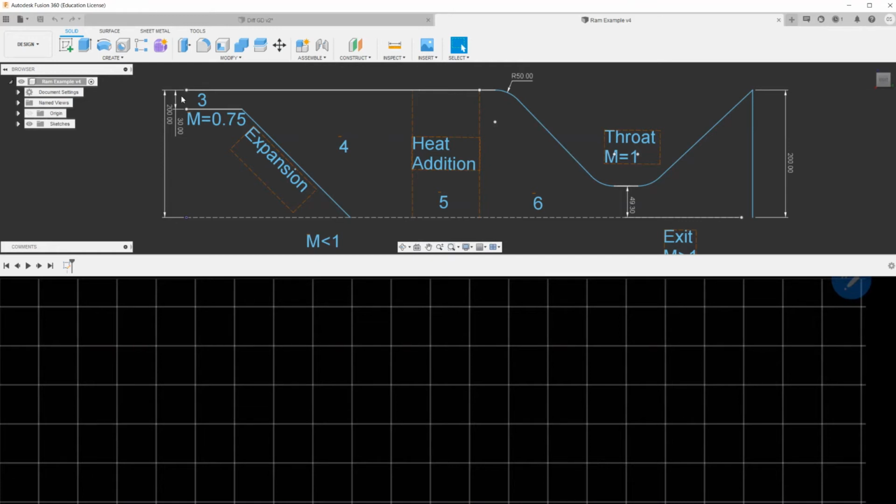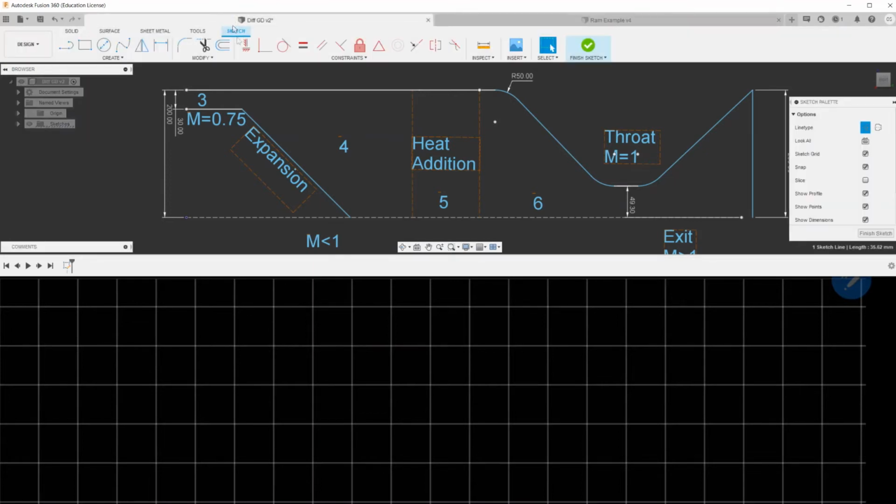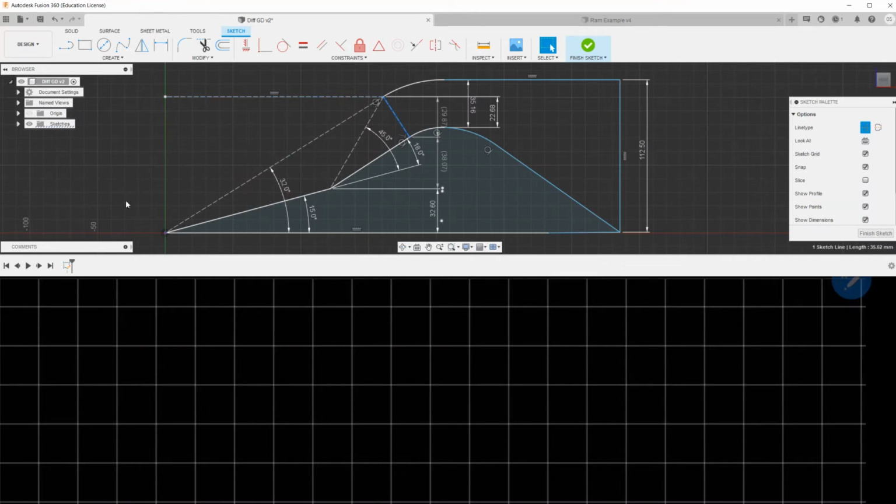Exactly. You could not forget that all parts of your calculation, like the shock wave in region 3, must be compatible with each other. They must be compatible because we physically have this mass flow rate since the beginning of the calculation. It's not possible to pass a different mass flow rate than you have here. Air is coming inside your system, so it cannot be pushed outside by limiting this size here.